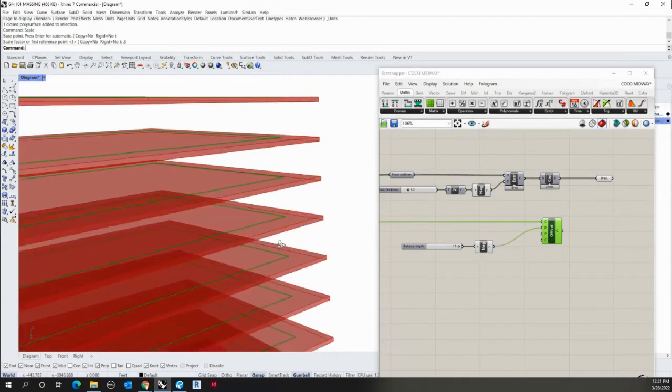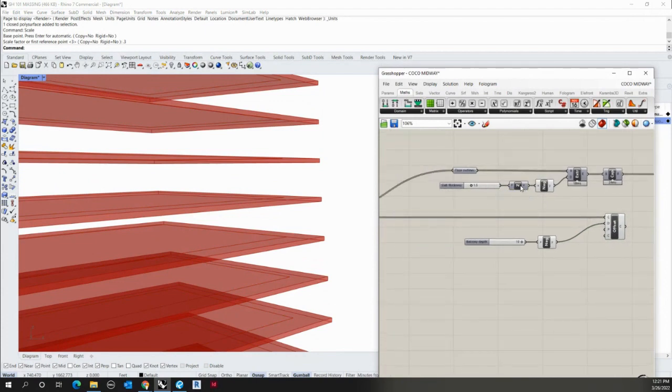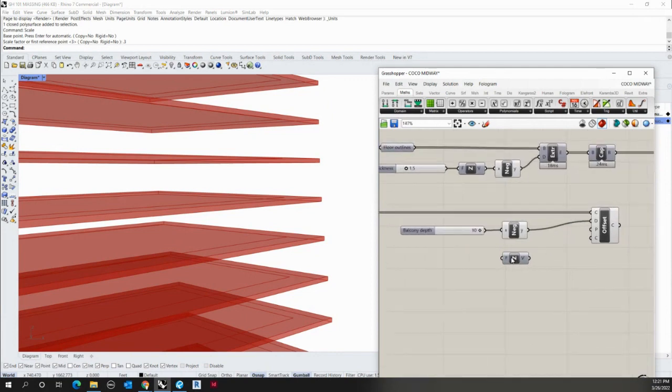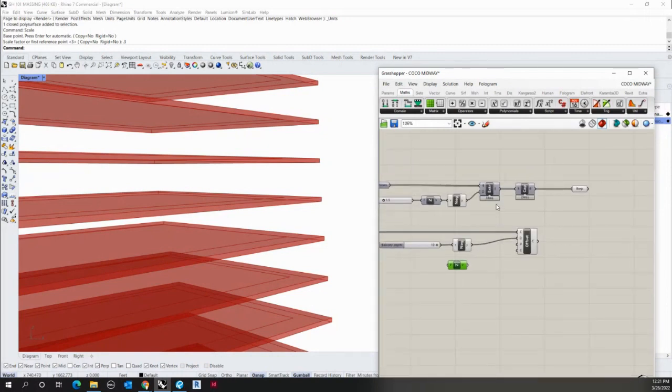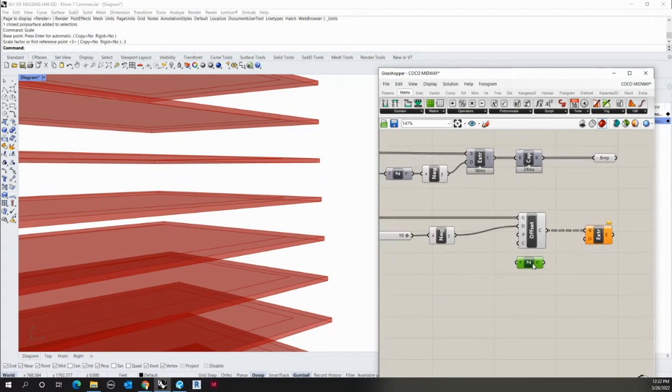So now I can extrude my facade upwards. And I will use kind of the same setup here. I need a Z vector going up. So I'll get there. And I'll plug this into my direction. Actually, I need to extrude this curve. So this curve is what we need to extrude up, just like we did for the first step of the slab. So using the extrude tool, I use my base curve of my facade. There we go. And it's still missing the direction and the amount.